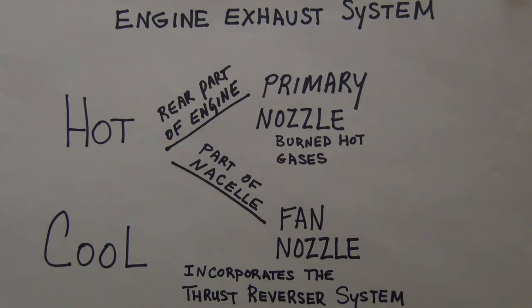All right. And as far as the sensitivity, there's different degrees on the throttle lever. Remember I said that you have the thrust reverse levers on the throttle levers, which you do. There's that throttle lever angle. And there are certain degrees where, once it reaches a certain number of degrees, you have the deployment or the execution of the thrust reverse.